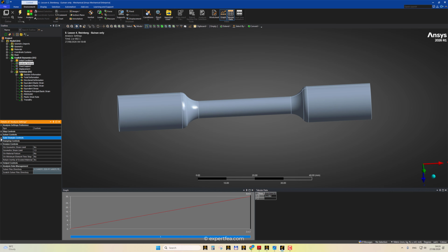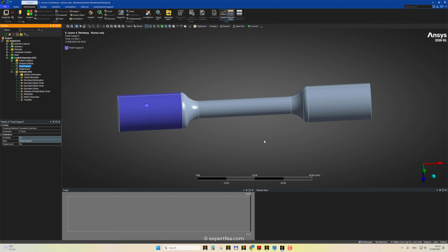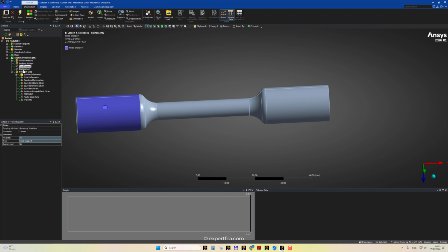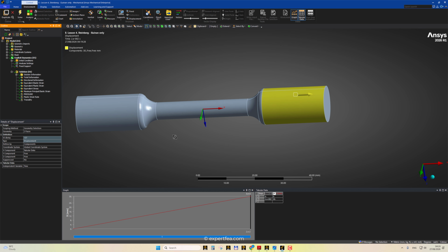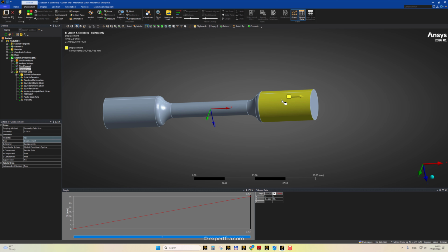In this particular simulation, we kept the default geometric strain limit. One end is fixed, of course, and one is displaced, not force. We don't use a force here. Using a force would imply a shock.